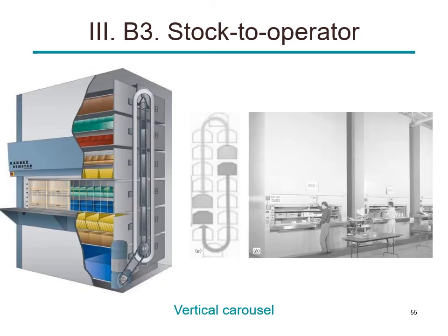Similar to horizontal carousels, we may have vertical carousels in which the items are placed on the racks, and the racks are turned on a vertical axis. So that again, the operators collect as soon as a rack is in front of them. So you see this is a vertical carousel. Usually they are closed, only a certain window is open, so that when you ask for a rack, it automatically brings that rack in front of you and you collect the items.